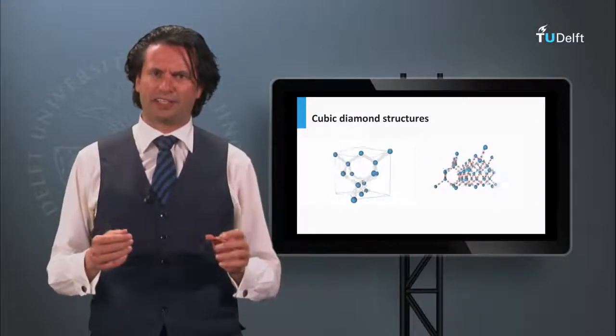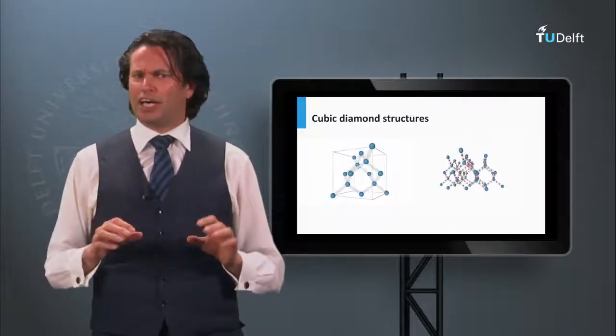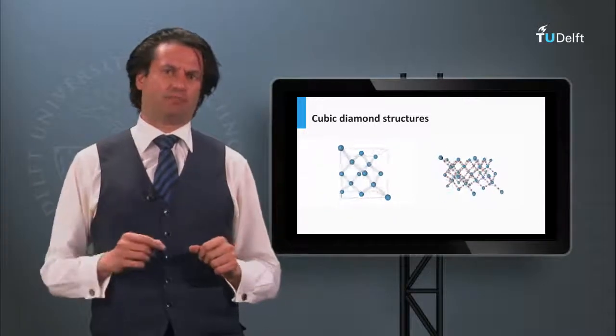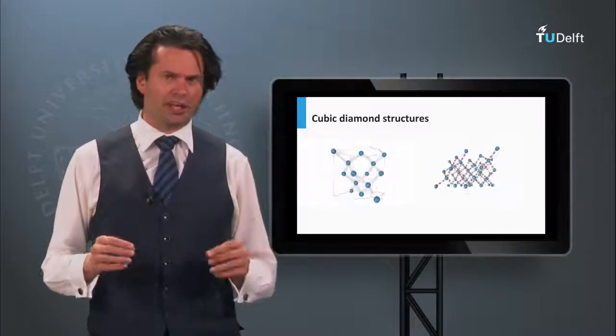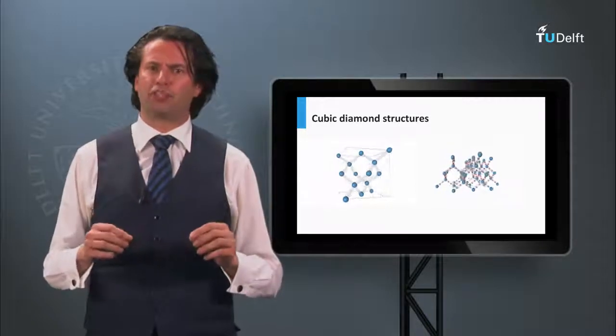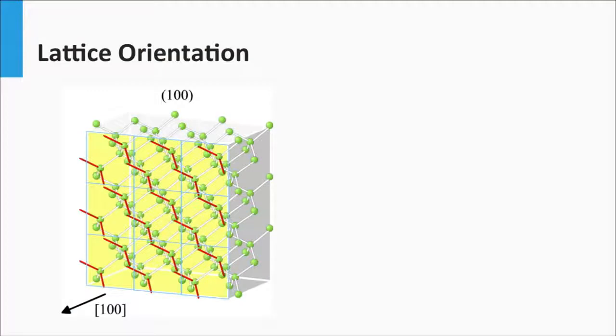A crystalline lattice has long-range order and symmetry. However, it does not mean that this pattern is the same in every direction. Or in other words, if we make a large cut through the lattice, the various planes you can make do not look the same. Here we see two planes of two different cuts in a crystalline silicon lattice, which originally consisted out of 3 by 3 by 3 unit cells.